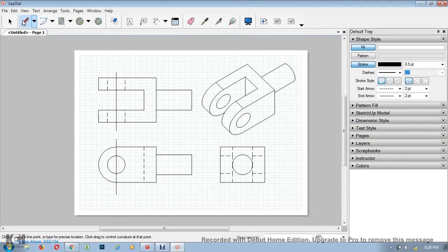I'll click this one, and the line thickness you see is 0.5, so I'll change it to 1 point and click in the middle, click somewhere here. Now if you don't press escape, it will keep on asking you to give the next point, so I'll click escape to close the command. Again I'll click here and here and escape, as well as with reference from here, click, escape, as well as middle point.